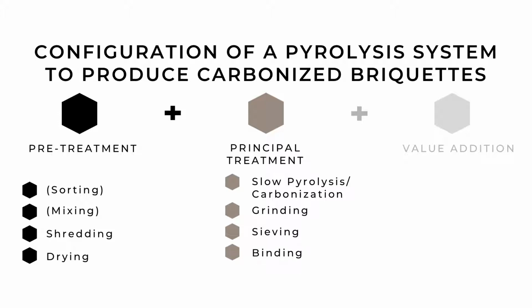Binding is the process of sticking together the compacted material. Due to loss of binding elements in raw materials during carbonization, a binder with high binding property needs to be used to create a solid form with the densification into a mold. Common binders include cassava flour, molasses, wheat flour, fine clay, and red soil.